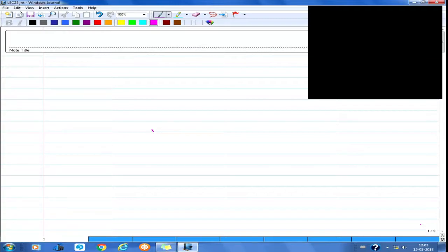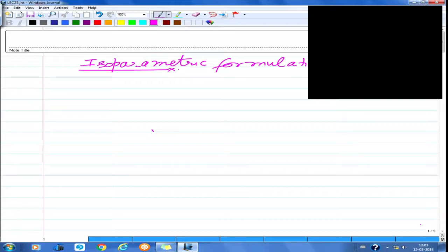See, so far what we have done is we were discussing, there were a couple of questions. We were discussing about isoparametric formulation. So one question was, how do we decide when to use subparametric, when to use superparametric or isoparametric? So the answer to that question is, most of the time we actually use isoparametric, and you hardly find the use of superparametric finite element formulation. But in the isoparametric, actually your subparametric is in fact included.